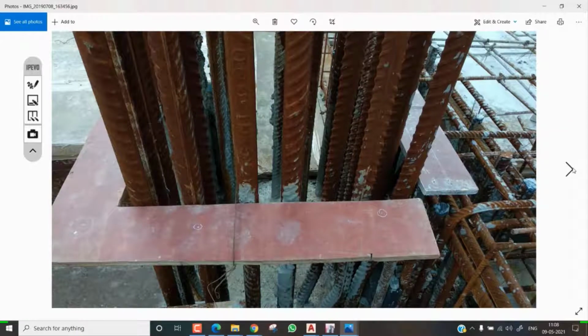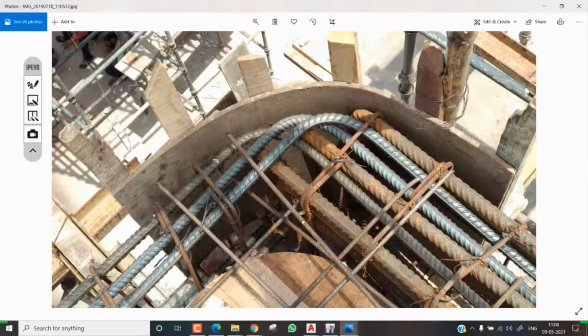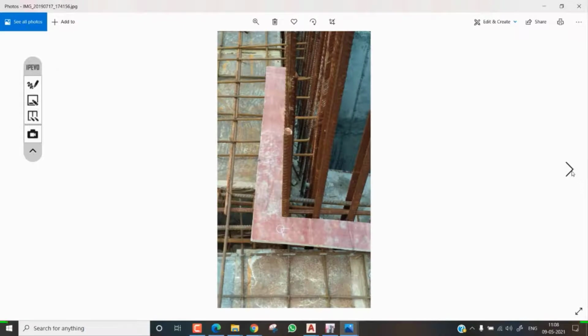So here are the total station points, and after that you can imagine it. Can the 20 mm aggregate go inside this? At that time you need to go for some 10 mm aggregate also. Most of the mix designs will include both 10 and 20 mm.